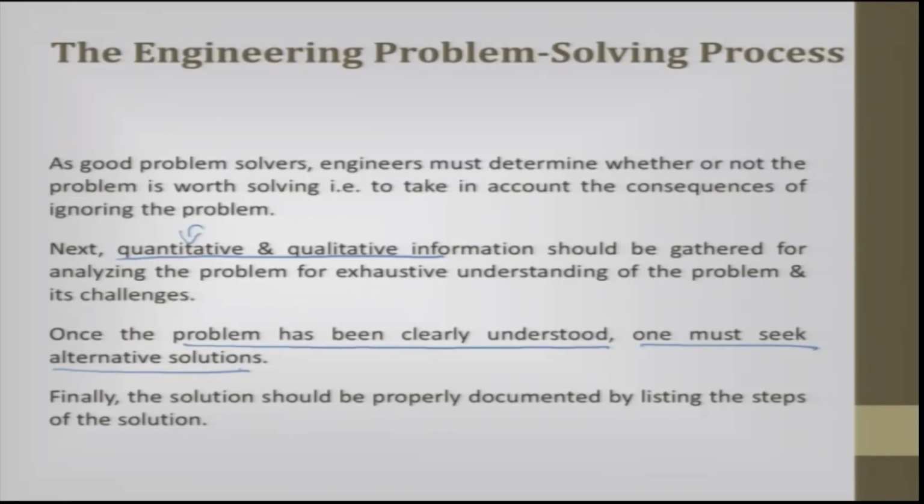For example, I would like to have a cell phone which needs no charging for 10 days. You have not specified what all the apps are. You have not specified what is the time you use your mobile phone. So, you have to understand all those things, convert them into numbers and come out with, okay, this is the total time he is going to work on a mobile phone, this many apps he is going to use, for this what should be the consumption of power, and for that power what should be the battery, and then we decide what should be the recharge cycle time. So, like that we have to go ahead, converting qualitative into quantitative data has to be done.